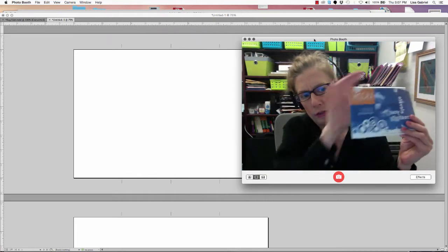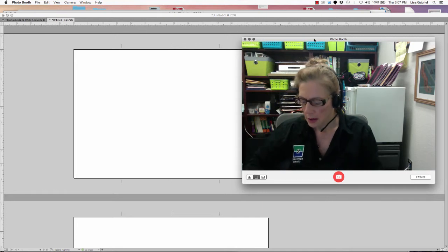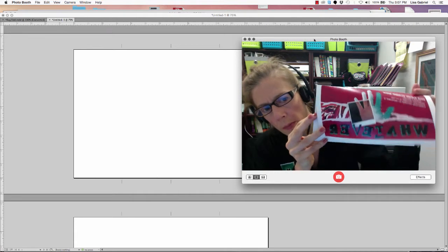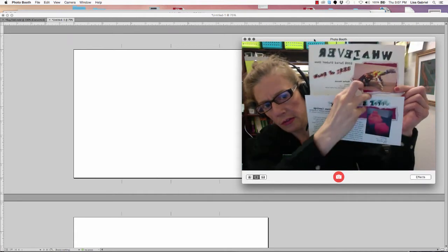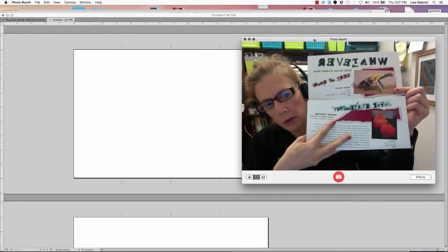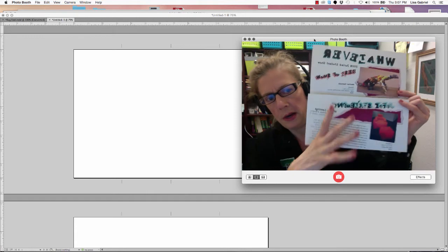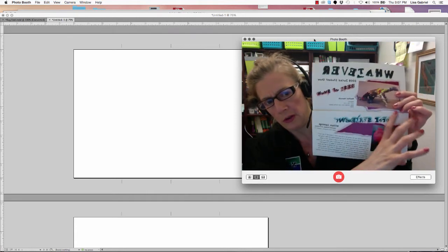Let me show you a simpler version of this. I've got it here. So here, they call this the barrel roll, where you open it up like this, and this kind of rolls down. This is a simpler version. In a barrel roll scenario, you do have to calculate the shorter fold because this panel right here folds inside this one and that one folds over. So this panel right here needs to be shorter.